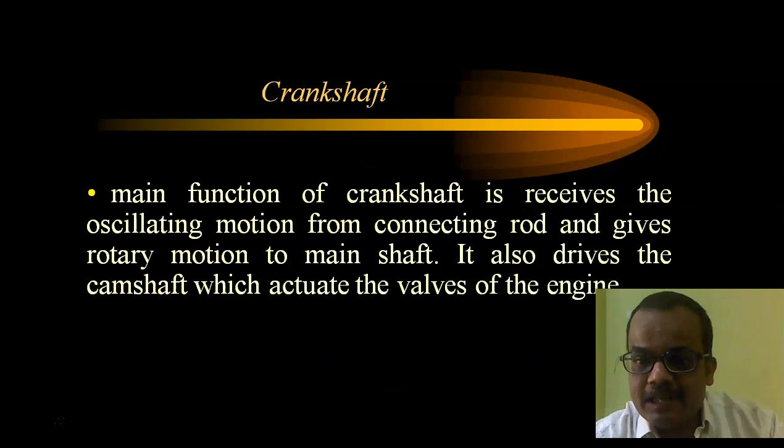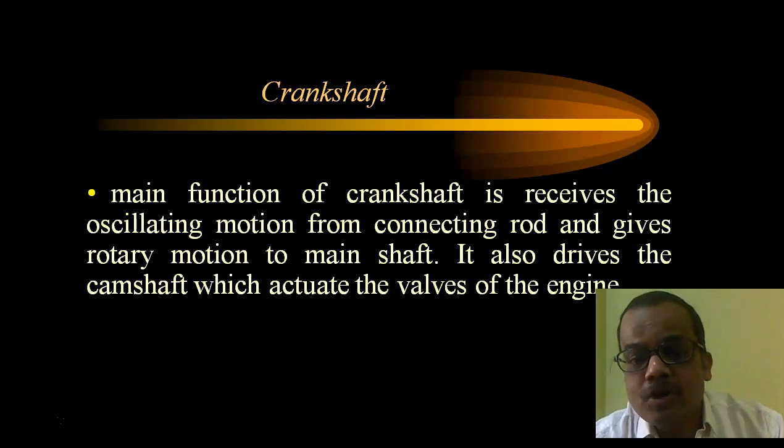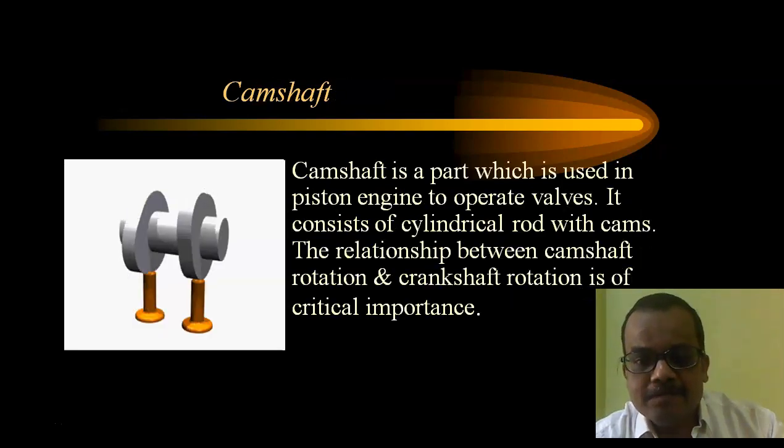The main function of the crankshaft is to receive the oscillating motion from the connecting rod and give a rotary motion to the main shaft, and it also drives the camshaft. A timing chain connects the crankshaft and the camshaft, so the crankshaft runs the camshaft.